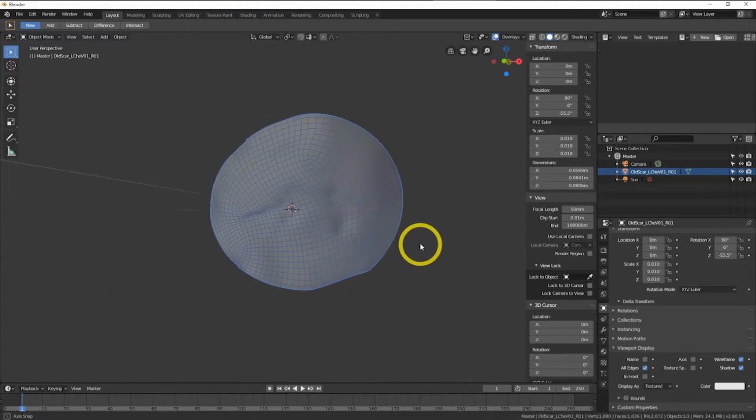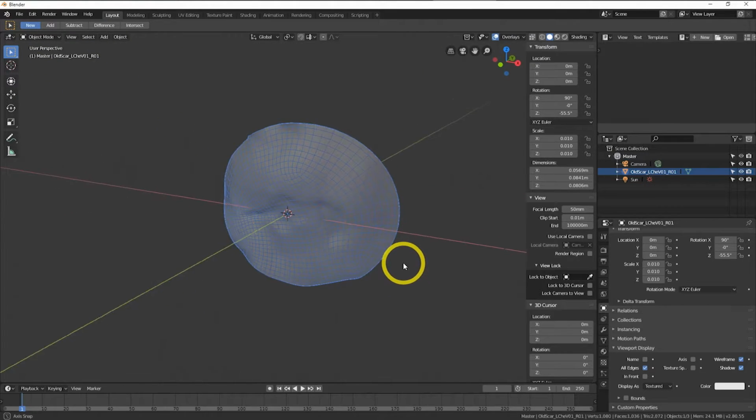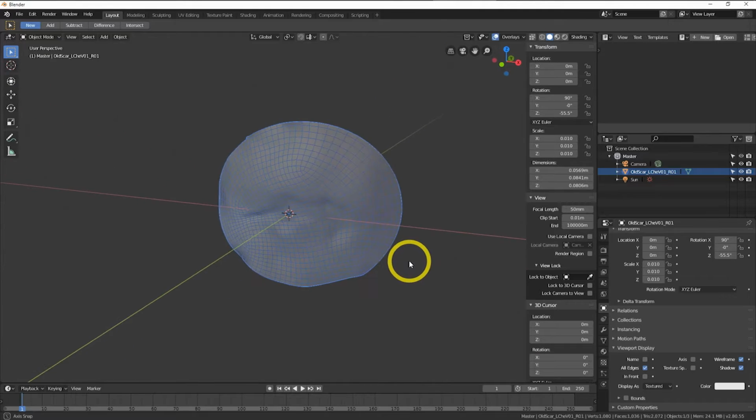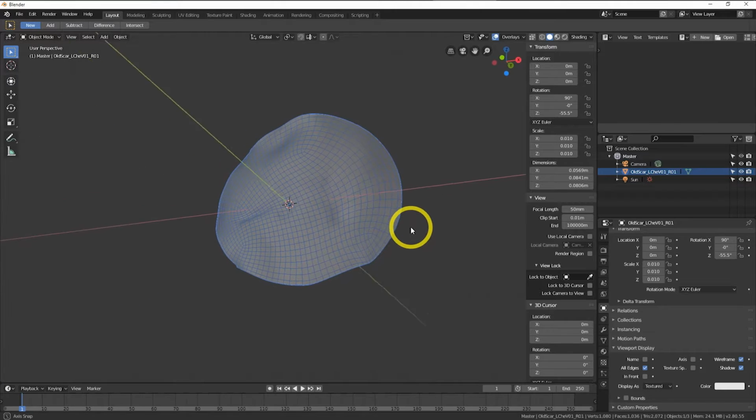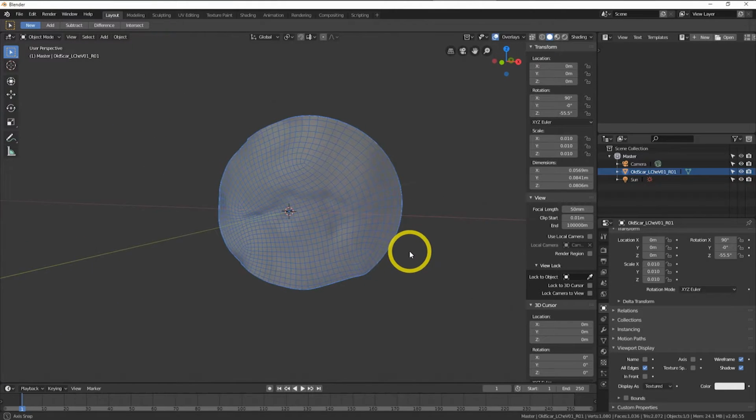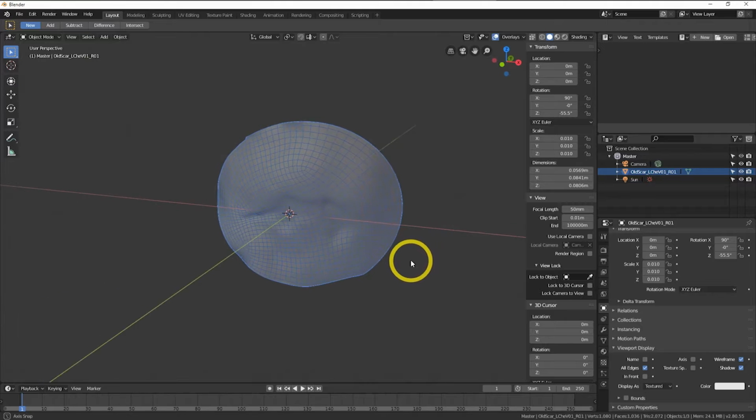And the surface is made up of what we call quads, and mostly this would work fine, but FBX is a bit touchy and sometimes it prefers triangulated meshes, and this is not a triangulated mesh, this is a quad mesh. And the best thing to do to fix it for Fusion is to triangulate it. Now other systems don't seem to have a problem. For example, I've used Alembic before in Fusion, and that doesn't have an issue importing Alembic files, but FBX can sometimes not import because of this issue.